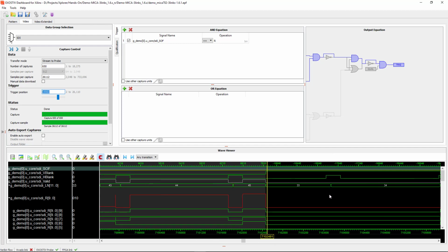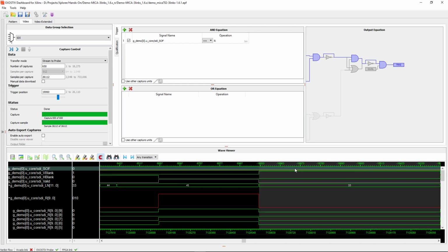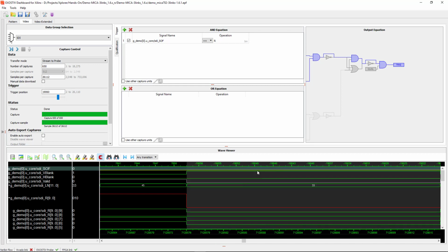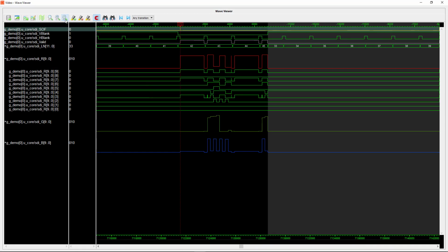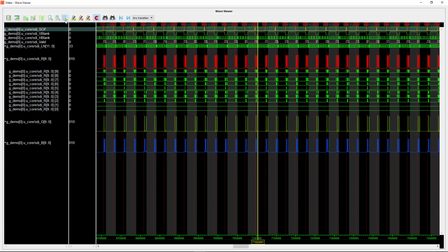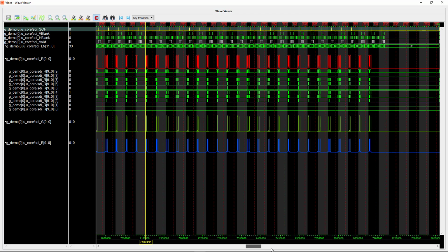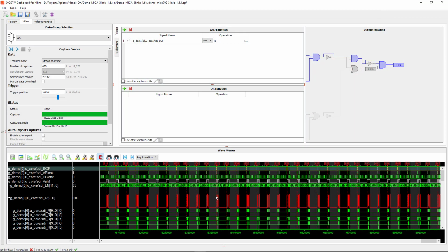If we check the end of each capture, we should find about 7,000 samples after the trigger, because the total is 26,000 with 19,000 before the trigger. That's what you see on the top scale of this window. Finally, we can check that we have indeed collected 650 triggers. They are numbered from 0 to 649.